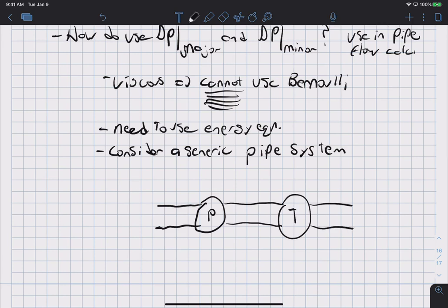Okay, and so what we're going to do is apply conservation of energy, and we'll just choose our control volume to go over the inlet, the outlet, and over the turbine and the pump. And so I'll call this section 2 and section 1. This is to be consistent with your book. And we'll have a W dot in from the pump, a W dot out from the turbine, and also we'll have a Q dot loss as heat goes out.